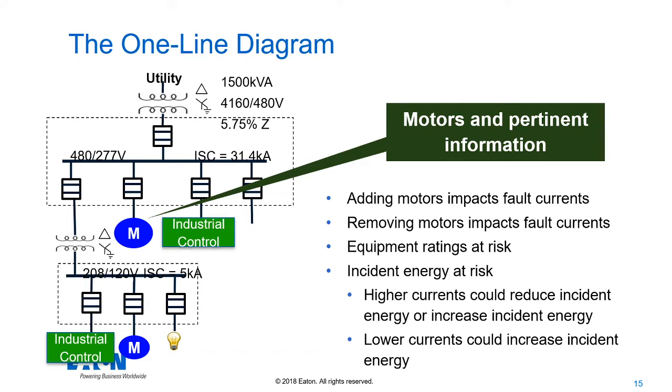The impedance of the motor is not typically shown. We make some assumptions when we're doing fault current studies and things of that nature based upon impedance, but you'll usually have the horsepower of the motor that's installed, especially the larger ones.